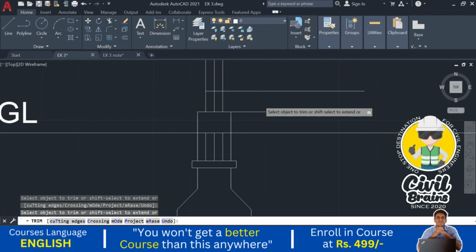Whatever walls we take, these are the partition walls. For the partition walls, there is no need to provide that one. I'll show you how much we need to provide. But for the main walls we need to go to a certain depth. So in this project we have taken the depth of the foundation for this wall as 0.45, sorry, 0.5 meters.